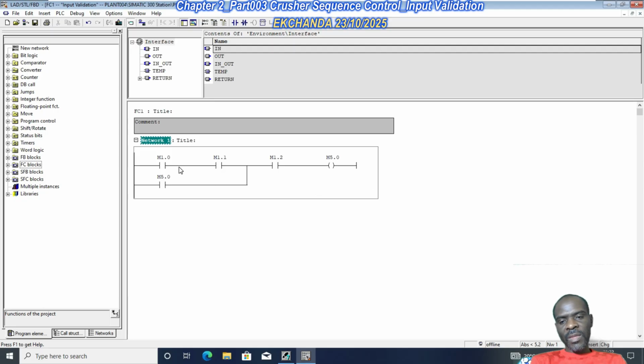So this is basically just a typical configuration. Now we're going to make some assumptions. The inputs we're most interested in are protection inputs, and our protection inputs are all going to be wired through normally closed voltage-free contacts.